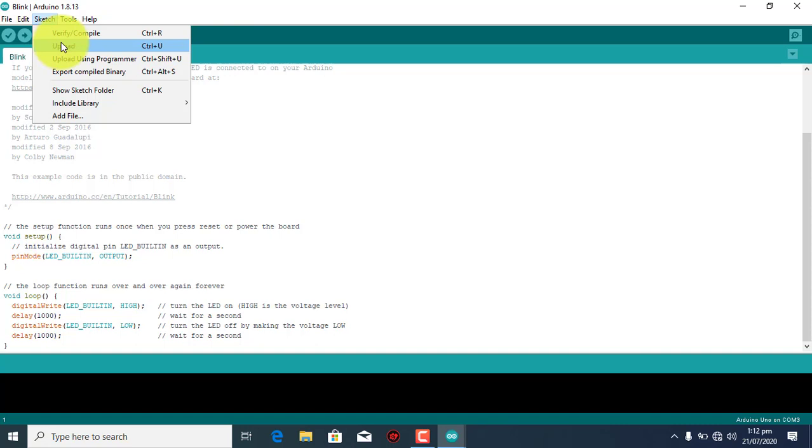Maybe if you want to use the Hex File to program, let me say, like for me, I learned the hard way, which is I designed my own demo board, which I was not using Arduino for the first time. So for me to program my ATmega328, which the Arduino Uno uses in their Uno board, what you just have to do is generate the hex file. What you just have to do is export and compile binary.